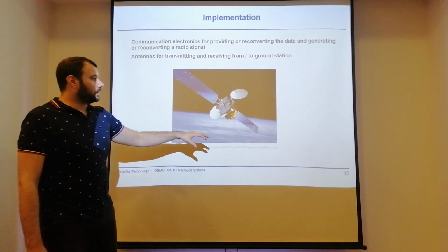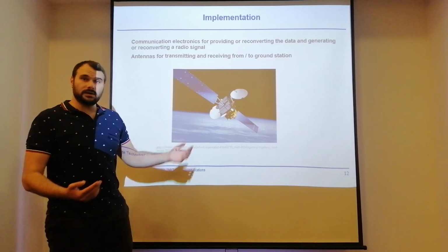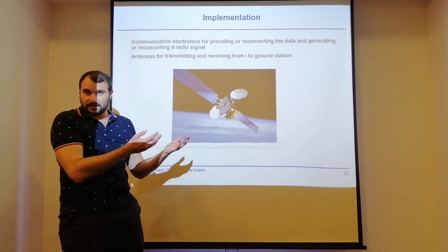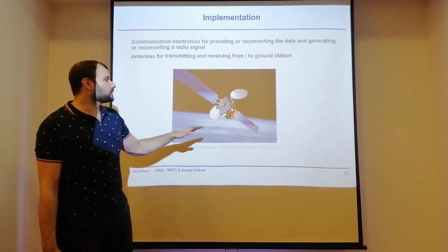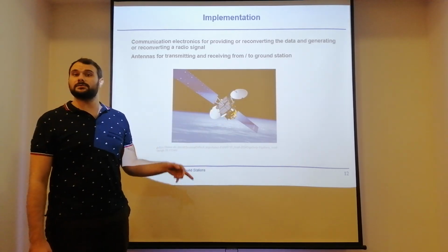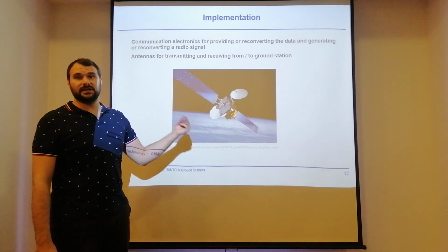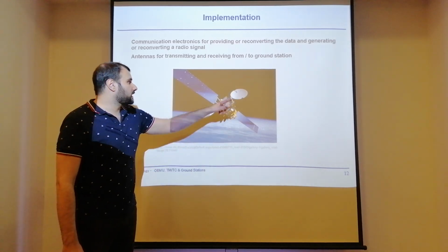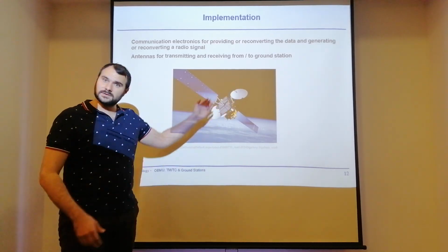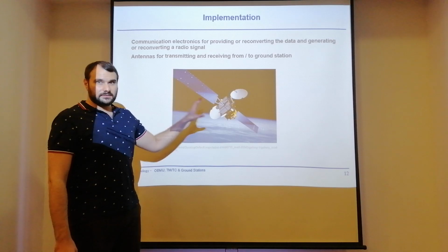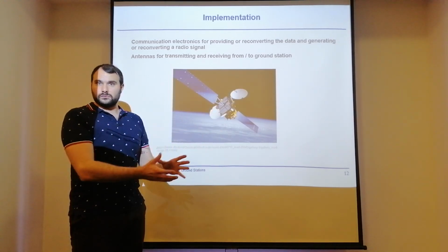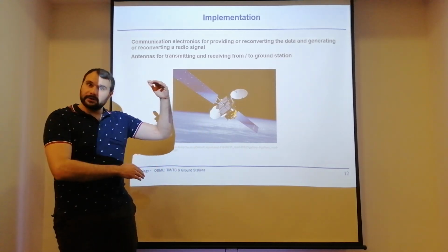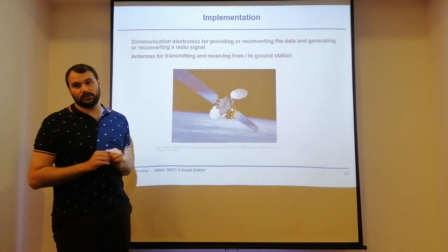In general, what we also can do is not just to receive our uplink signal, do something and send a response, but they could also straight send it back down as a relay. And that could be regenerative or transparent. Yeah? Transparent is we have a straight connection, we only change the frequency, it goes back. But regenerative would be that we actually improve the link, we reorganize it on a different layer, reorganizing it and then send it out back again.